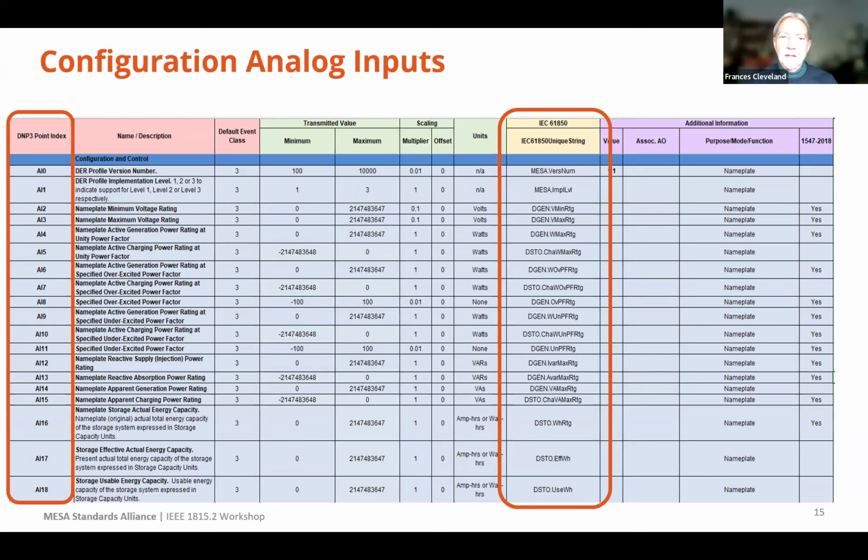I will also point out that some of the other protocols, such as IEEE 2030.5, also use the 61850 as their base, sometimes with slight changes in the way they're expressed, but they're the same points with the same meanings. So we're really beginning to come together, at least in the semantics, the meaning of particular points. So this means that even with IEEE 2030.5, there can be an easy mapping between the different protocols. But we're talking DNP3 because so many utilities use that and need that for SCADA-like interactions, in particular, the larger systems.